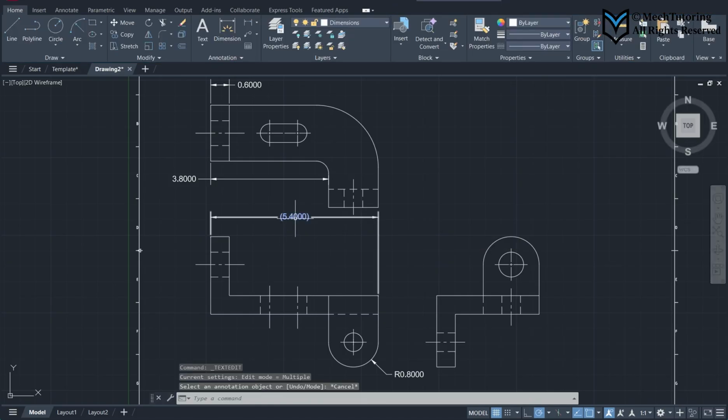But why do we need the overall length if it was already done over there? Because in some engineering drawings, we have to mention what's the overall size of the object, okay? Even though we can calculate it, we don't want whosoever is reading the drawing to calculate it. I want to tell that guy that overall length is this much. You don't need to pick up a calculator to find it out, okay? Because sometimes the dimensions are in decimal points, so it's hard to add them up. So I give the overall length in that case. So that's the reason behind it.